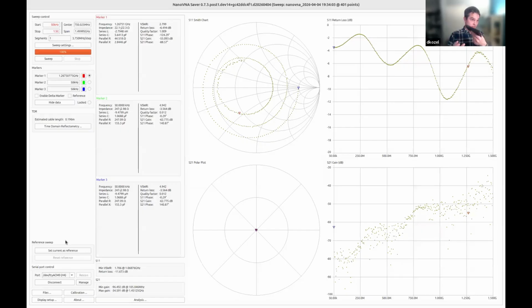An interesting point on the NanoVNA specifically is that you need to hit the reset button first. So if you go into the calibrate menu and you hit reset first, that clears out the calibration that might have been there before, and you can start plugging in the pieces, starting with an open. I'll start running through these.